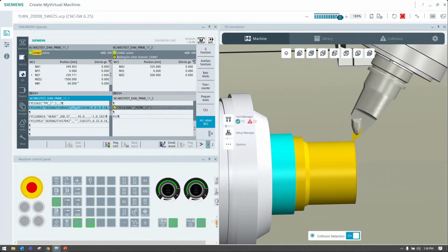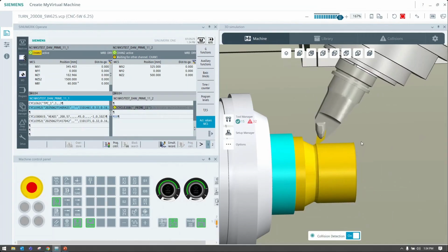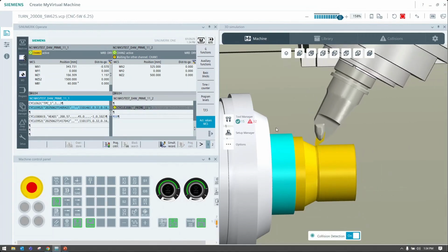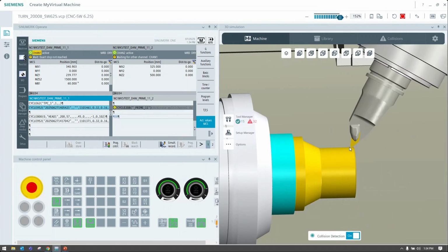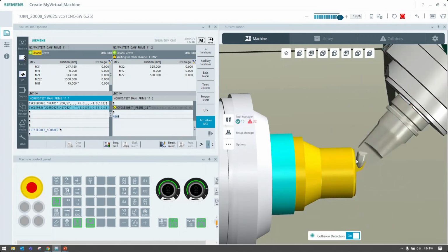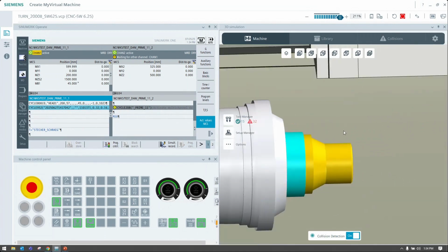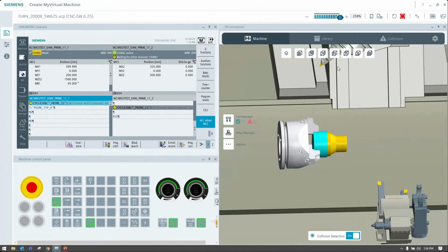And then as I'm starting to do this, I can utilize that and then come back the other direction and finish it. So again, the premise here, you're saving on tool changes, right? There I just did that for an orientation change, but we could have definitely oriented right there. But as you can see, I pulled and roughed in one direction, and then I came back and finished the other like a traditional insert.